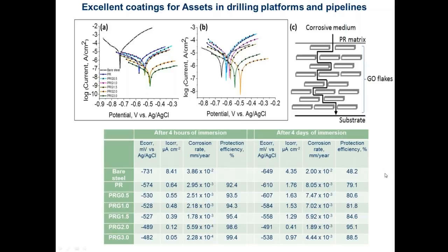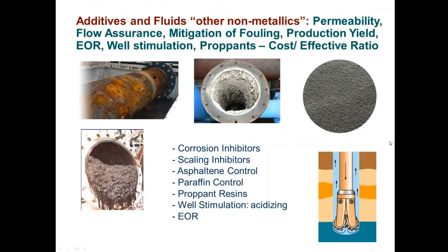On the other side, which is, by the way, the typical solution for corrosion, are basically hermetically sealing the other side of the carbon steel, let's say, from the corrodant environment, whether it's sweet or sour corrosion, biogenic, abiogenic, H2S, or simply water from produced water and brine.